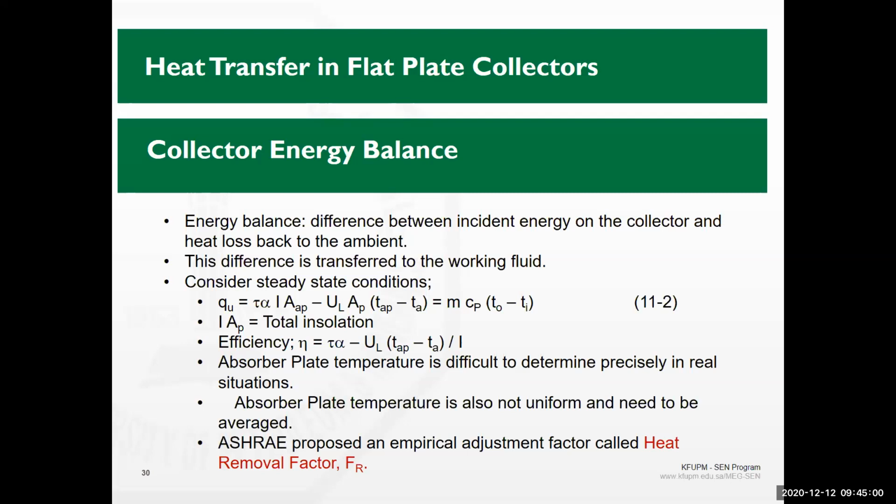The equations that we have here are simple and straightforward, but we have an issue with TAP, the absorber plate temperature. To overcome this, we are going to follow the approximation that ASHRAE has made.